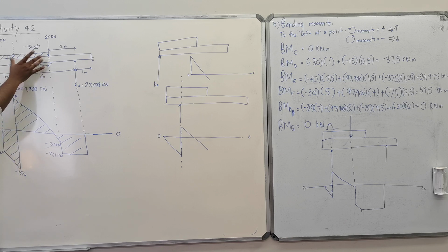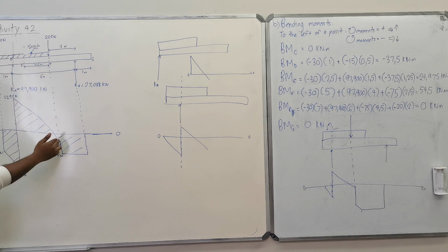For this here, we have that remaining 4 meters of uniformly distributed load, which I drew there. Then I have a downwards concentrated load, which I showed there, and then we have nothing for a while, so the line continues straight until the support brings everything back up to 0. Okay. Do you all understand what I'm saying? Does it answer your question? Do you understand? Okay, I think I understand now.